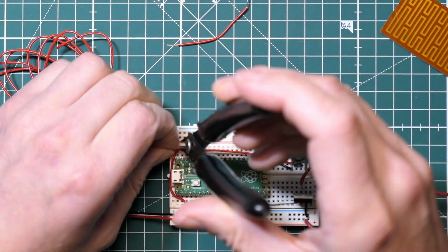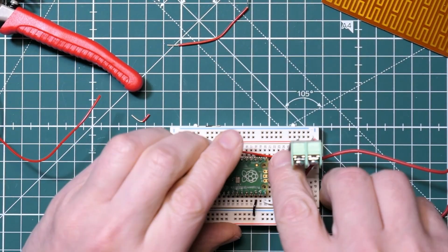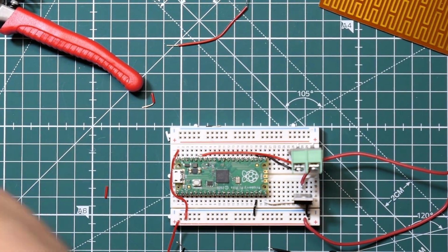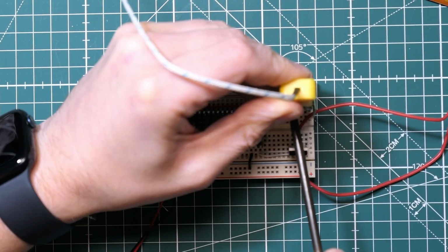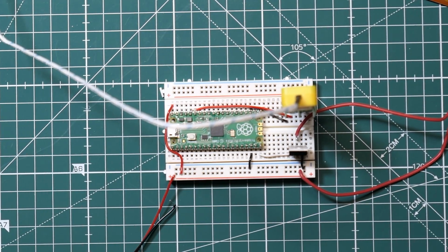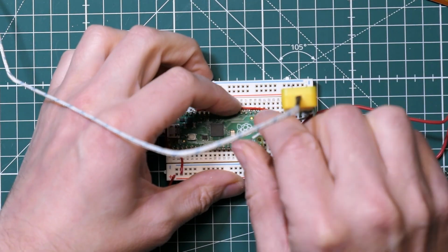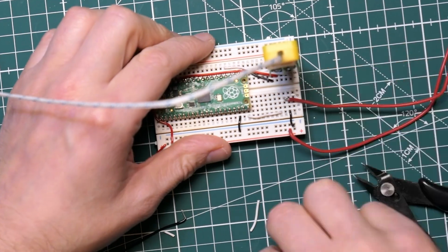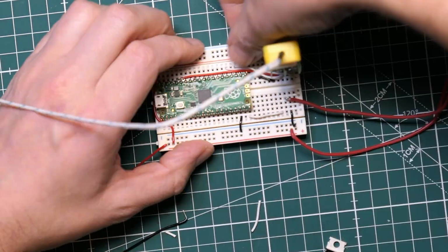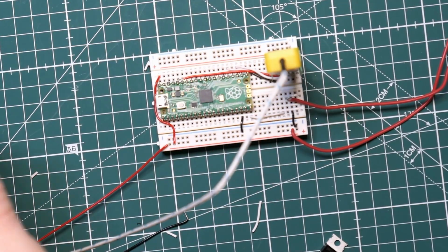It's quite a simple circuit. There's not really much to think about here. Just got to make sure that you don't put too many volts into your Pi Pico. And also, critically about the MOSFET switch, it must be a logic level FET. So if you just go and buy a random MOSFET from some supplier, chances are its threshold voltage is around 3 or 4 volts, which means the Pi Pico can't turn it fully on. Whereas if you get what's called a logic level FET, it'll switch fully on at 3.3 volts provided by the Pi Pico. So it's quite important you get one of those, or you might find your MOSFET's getting really hot and not properly switching. But other than that, it's a really simple circuit.